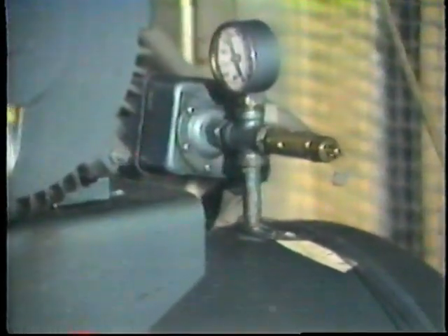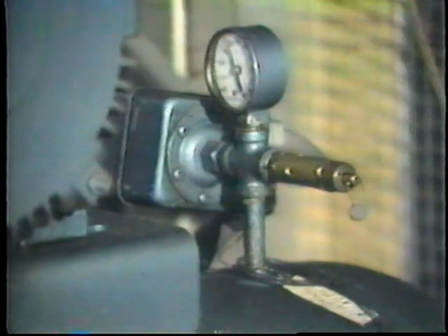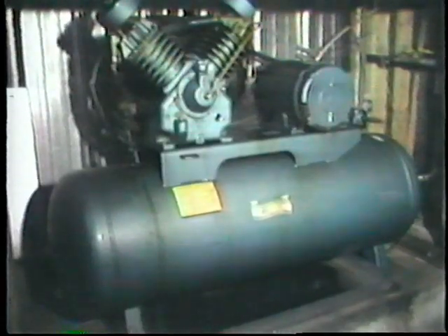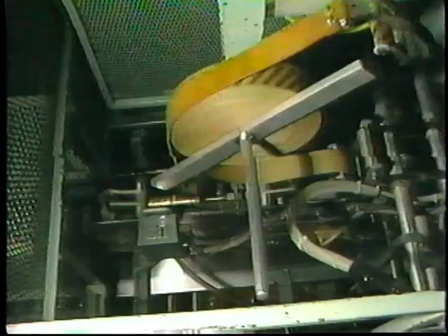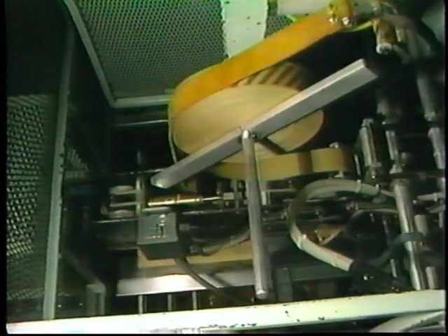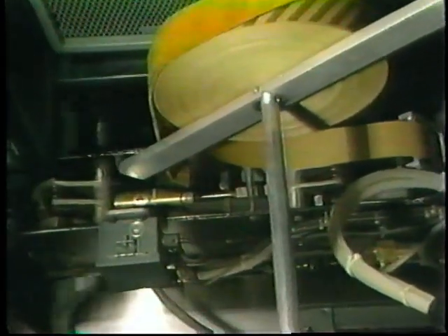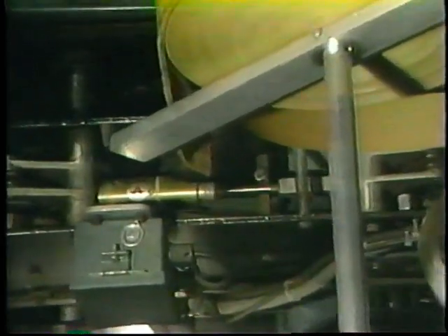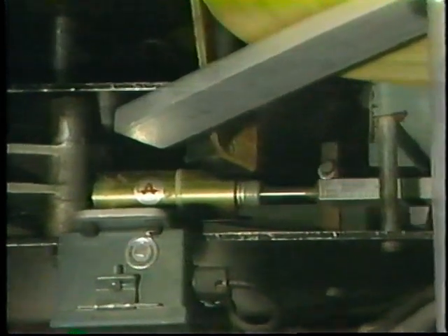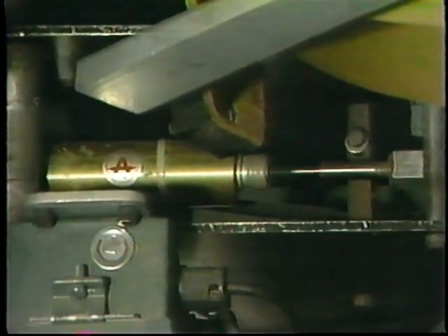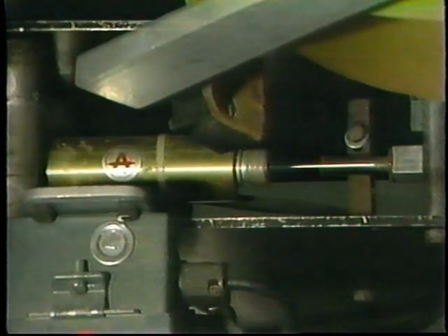If the pressure was allowed to rise uncontrolled, excessive pressure would be developed and the air receiver tank might rupture. Control of pressure at the point of use, such as at this actuator, is necessary for safety also. But more important, it assures that the actuator receives just the right pressure to operate without wasting air.